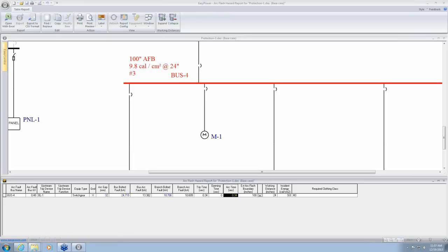Next question is whether fault time for total clearing consists of sensing and breaker opening time. Okay, I think this is something that I just answered previously when we talked about trip times and clearing times. So for relays with high voltage, we have to add the breaker opening time. For fuses and low voltage breakers, we do not need to.